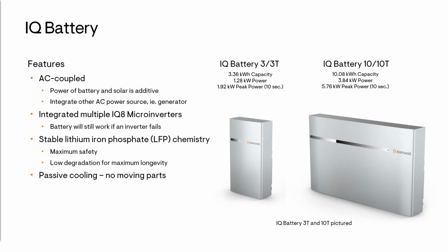Since LFP battery chemistry is inherently safer, IQ battery units have a simple passive cooling system. By that I mean no moving parts. For example, no pumps, no fans, no liquid coolant like some of our competitors do. By removing these moving parts, we're removing potential single points of failure from the system.